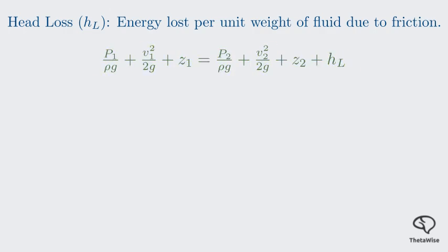Notice that I've divided the entire equation by ρg. This converts each term into units of length, or head. So we have pressure head, velocity head, and elevation head. This form is often called the energy equation.